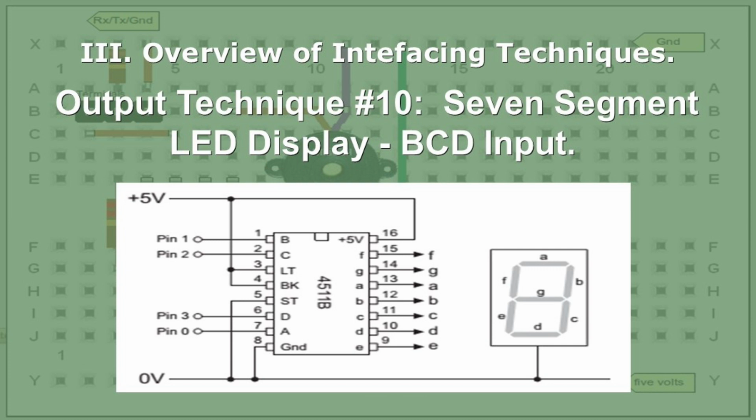If you put 0001, that'd be a high to pin number 1. No, pin number 0, I'm sorry. That'd be binary 1. Because 0 would be a low voltage on all 4 pins. That'd be binary 0. Remember your fundamentals. 0 is a number in binary. That's what they always reminded us of in electronics school. And in programming school, 0 is still a number.